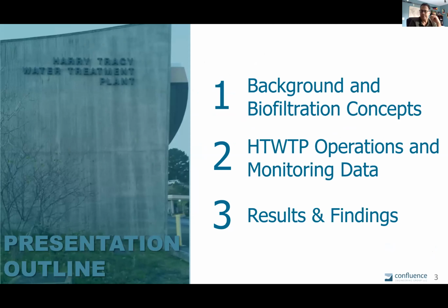What I'm going to go through in the talk are a little bit of background and some biofiltration concepts, some ozone biofiltration concepts, and then get into the operations and monitoring data that was the background of the facility being monitored, the Harry Tracy plant. And then, of course, the results and findings of the monitoring program.